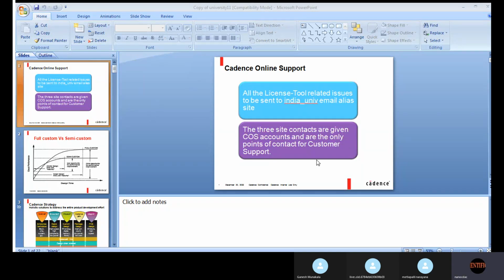Full custom design means that when you are starting the ALU which we have taken, you are starting from scratch. Scratch means every single transistor, every single cell, every single wire. Everything I am taking care of. I am starting from the beginning till the end, that means till the tape out. What I am designing is nothing but full custom design.